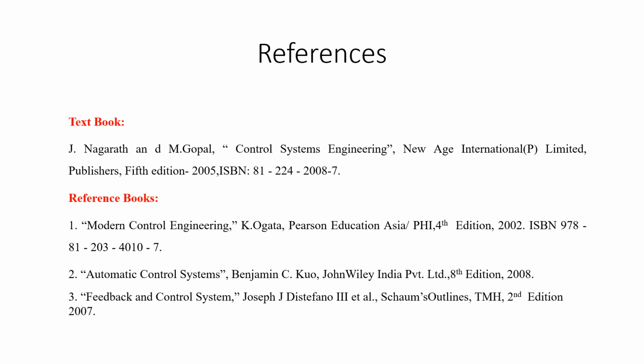Majorly you will have confusion in the third, fourth, fifth and sixth rules, because there you will be shifting the takeoff point, and in the others a summing point. Just remember when you will multiply the gain and when you will divide the gain, in takeoff points and similarly in summing points. You should know whether you are moving a takeoff point which was lying before a block, or one which was lying after a block.